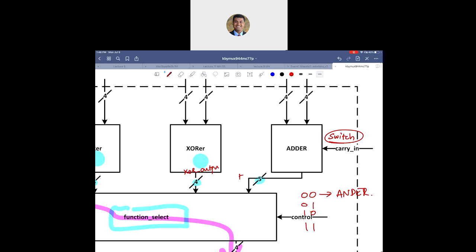Then the next question is, I added bit full adder 0 as a design source, but there's no code there. I would recommend that you save the VHDL files. Right click on those files on Piazza, save them maybe on desktop or some place on your computer with the extension .vhd, and then when you're ready, after you create a new project, you say add existing source and you select all the VHDL sources at once if you want, and then you can add all of them together.